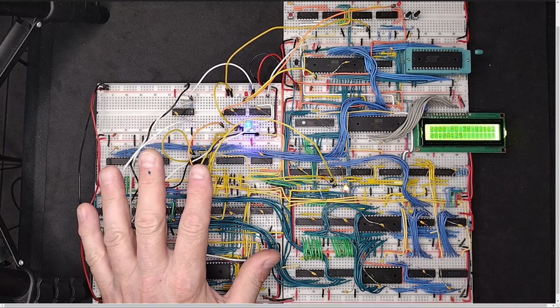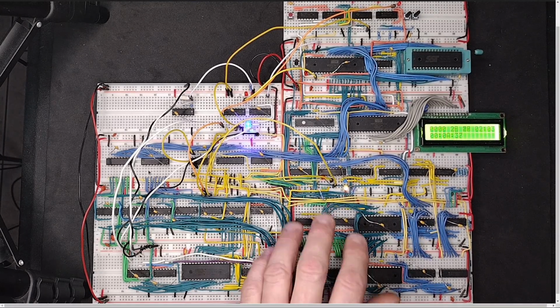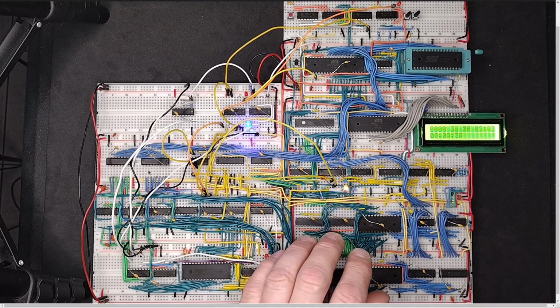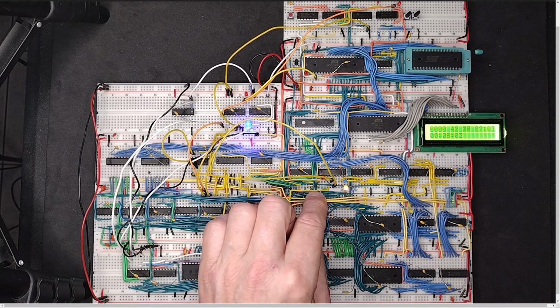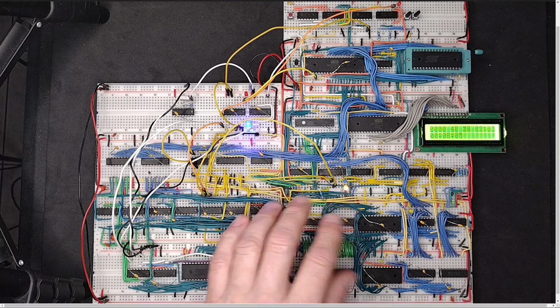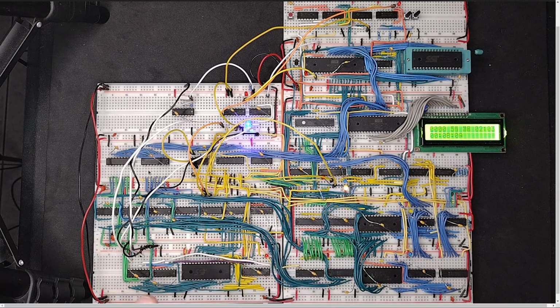Then what I want to do is take this whole board and shift it up so I can add more transceivers here. I need 4 transceivers. I need background RAM transceivers and foreground RAM transceivers that are for the use of the video card. Those will be active during the display interval, and these others will be active only when we're not in the display interval and when we're talking to the appropriate addresses. Then those transceivers will be active. So I need to move those up.